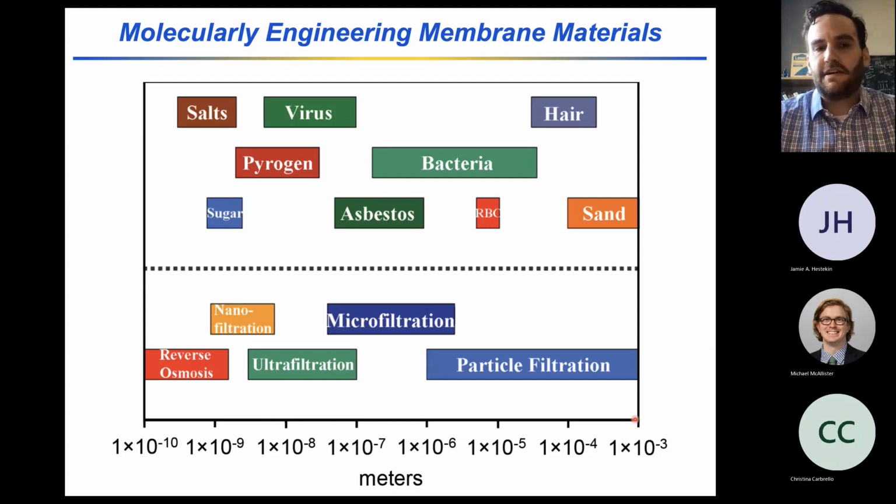In this instance, you're thinking about water filtration. An ultrafiltration membrane can allow you to retain viral particles while allowing the solution and smaller molar mass components to go through, and reverse osmosis membranes produce potable water by retaining the dissolved ions or salts.